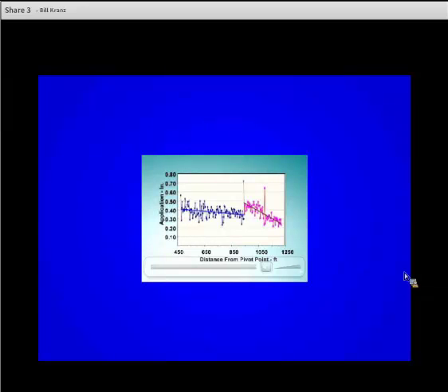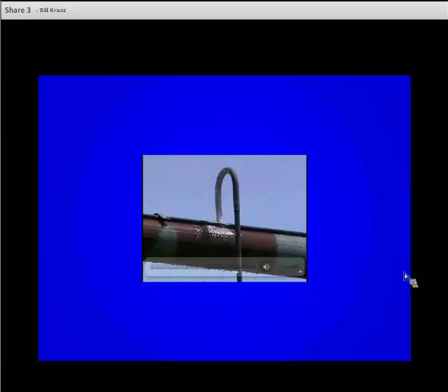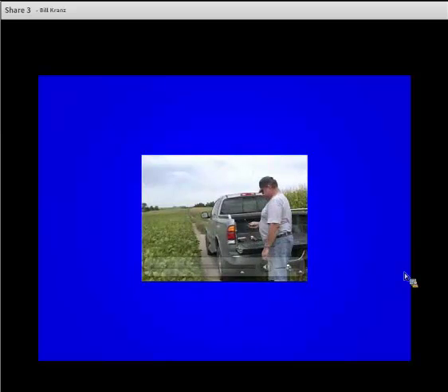Surprisingly enough, even with color-coded and numbers on the sprinklers, we still have some systems where the sprinklers are not put on in the appropriate manner. Again, this is some Kansas State data where the sprinklers in the last couple of spans were put on backwards. And maintenance here, we run into these all the time. I'm sure you've all seen them, geysers out there where the nozzle is actually blown out of the system. If you fly some of these systems where you don't get a whole lot of rainfall, you can see these issues quite easily.